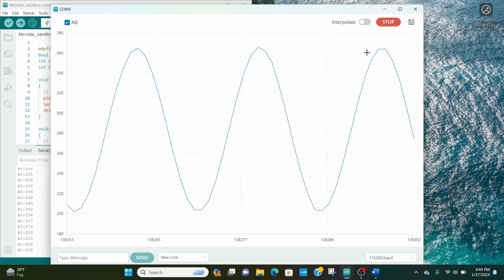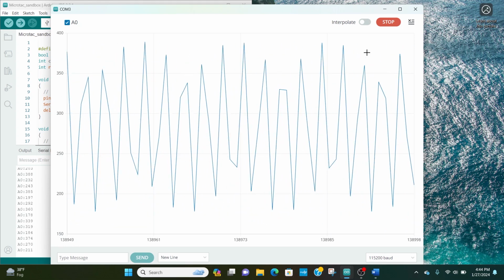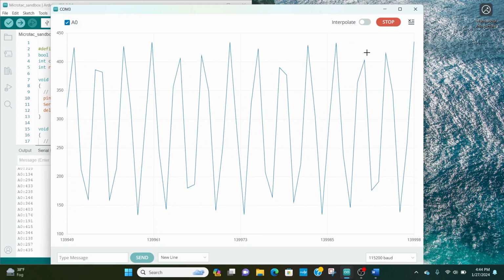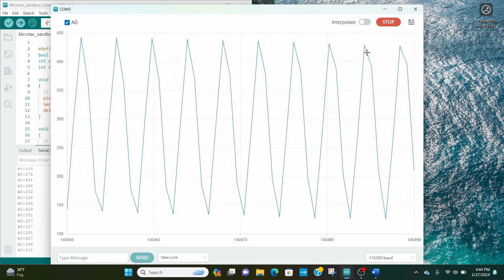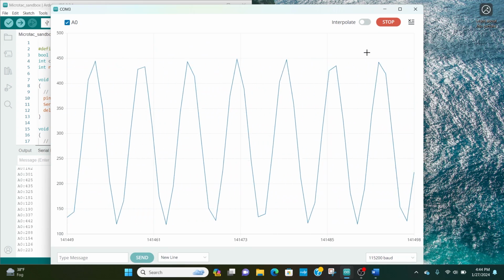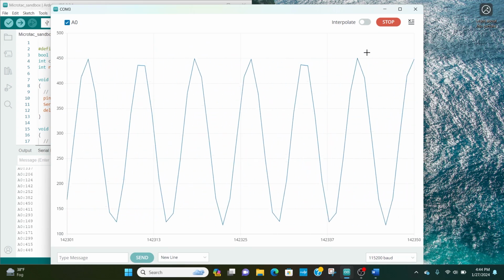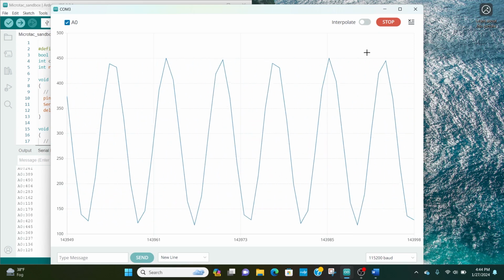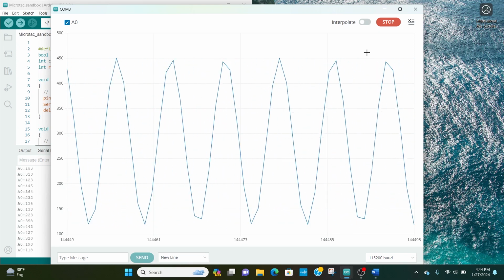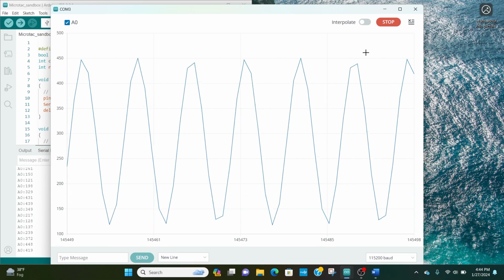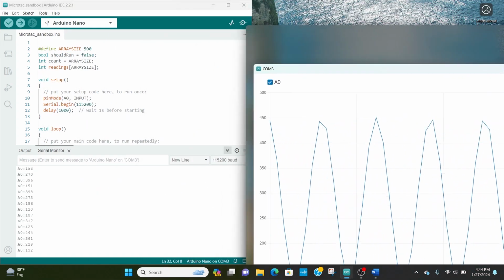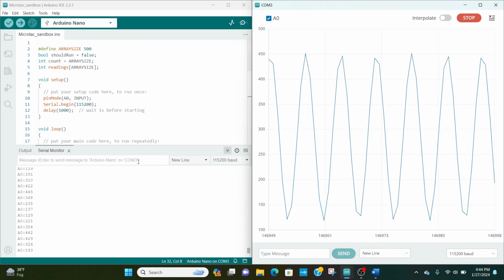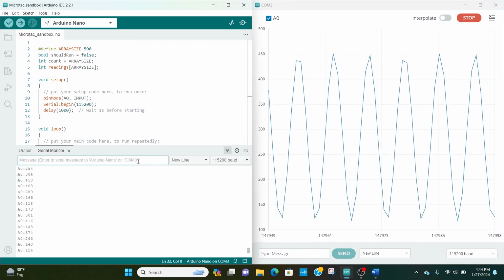Well, let me proceed to dial this back down to 1 kilohertz. So a couple of things. One, it might not be an issue. The amount of higher frequency components that are actually in the speech might not create as much distortion as I think, and it may sound just fine. That'll be what I find out when I actually hook it up, throw the whole chain together and try it out. I might need a more aggressive filter. Right now, I've only got a 1-pole filter there, so I might need something with more poles that will help roll that off faster. In the worst case, I might be fighting a losing battle here.